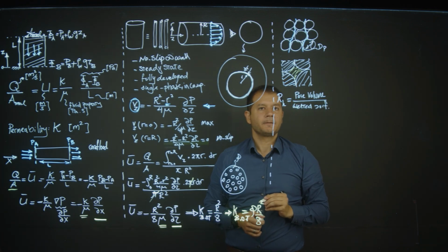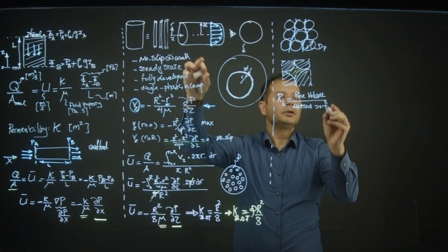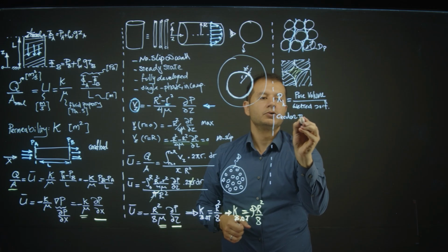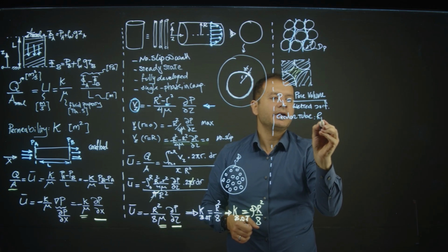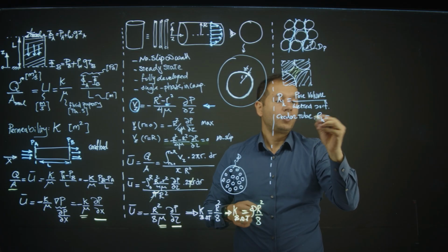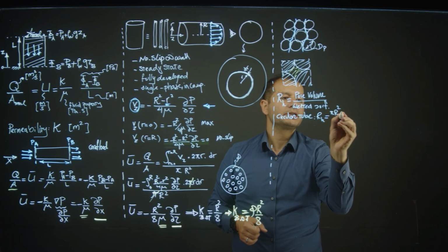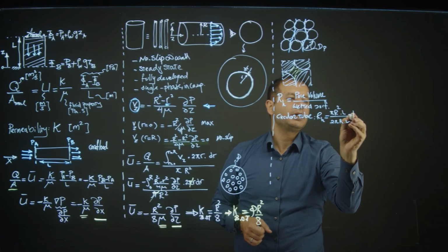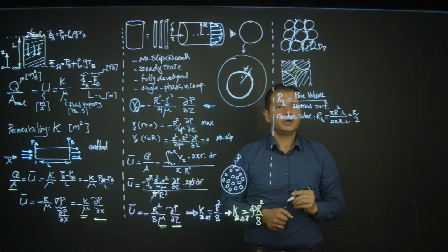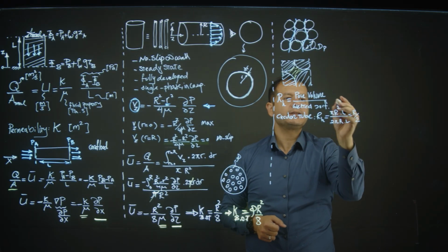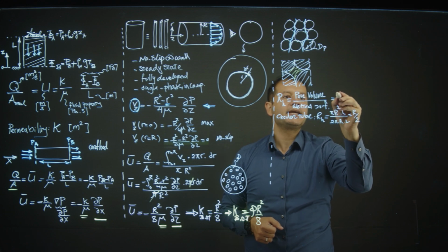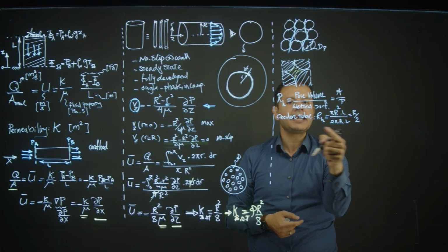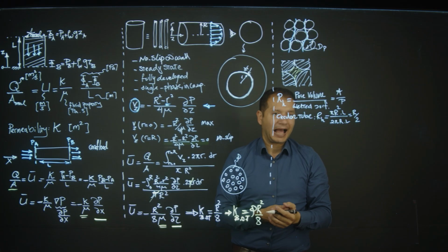Wetted surface. For a circular tube, hydraulic radius would be pore volume available, which is pi r squared times L, over wetted surface, which will be 2 pi r L, which will be r divided by 2, or half r. You can also calculate hydraulic radius, in some fluid mechanics textbooks, as the wetted cross-section area over wet perimeter. In that case, again, hydraulic radius of a circular tube would be half r.